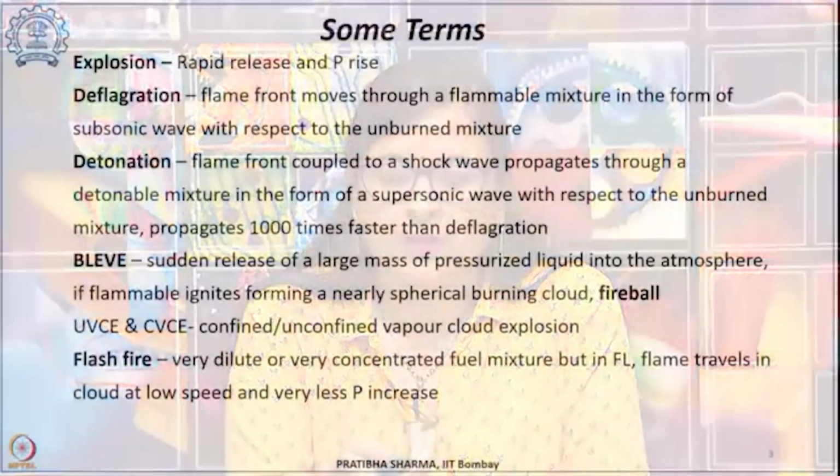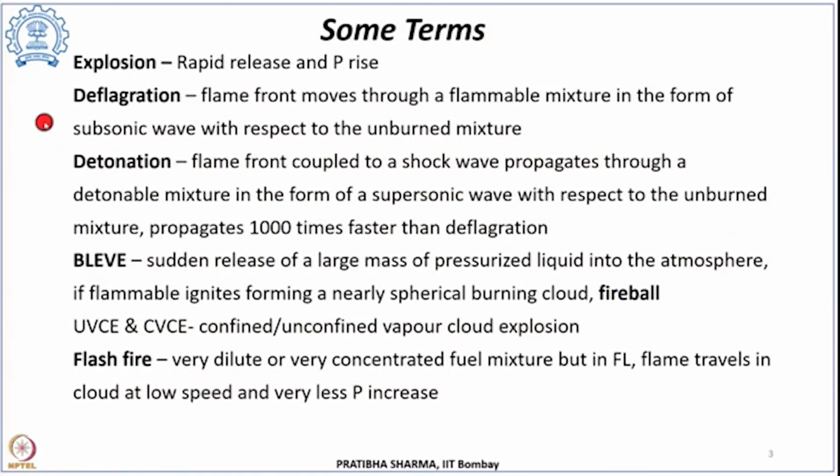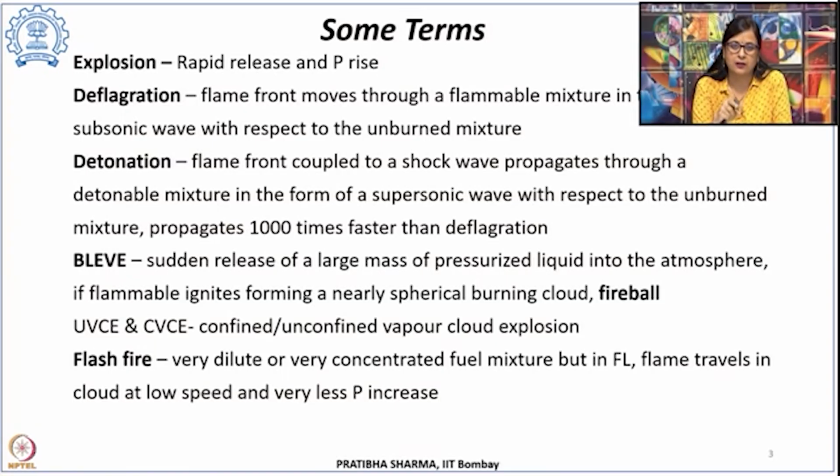Another term which is used in hydrogen related hazards is deflagration. Deflagration refers to the process where the flame front moves through a flammable mixture in the form of a subsonic wave, with respect to the unburnt mixture of hydrogen and the oxidant. Another term is detonation, wherein the flame front, coupled with the shock wave, propagates through a detonable mixture in the form of a supersonic wave, with respect to the unburned mixture. However, detonation causes much more devastation compared to deflagration, and it propagates 1000 times faster than the deflagration.